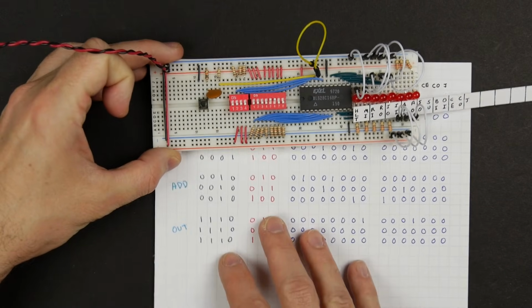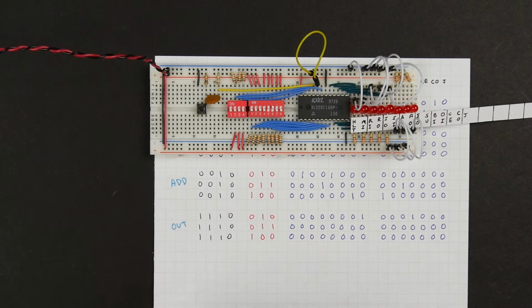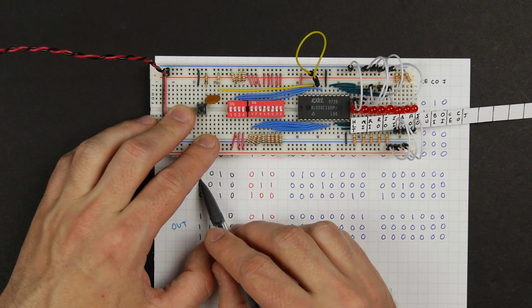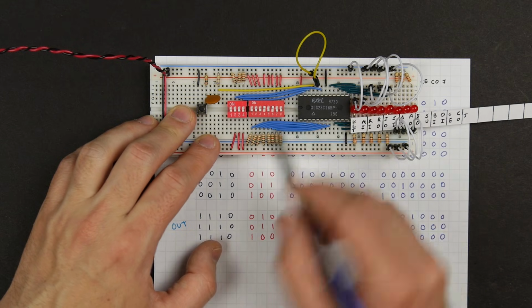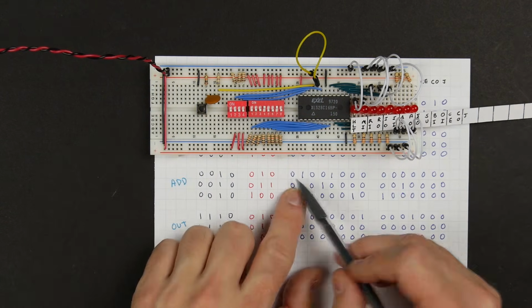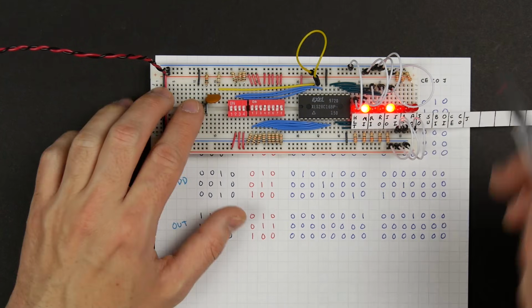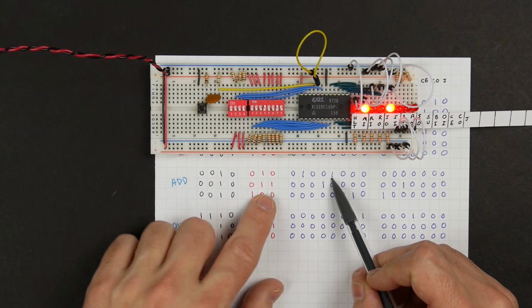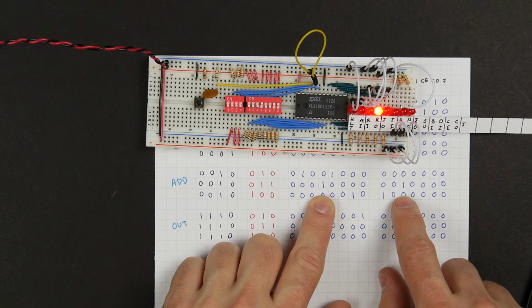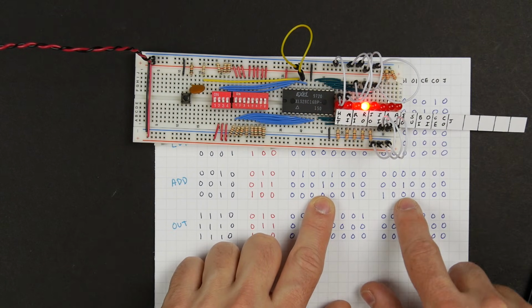So next we've got the add command. And so add command is 0010, the opcode for the add command. And then we'll go back to step 2. And so for step 2, instruction register out, memory address register in, that sounds right. Program that. Next step, that's RAM out. And then we're also going to do, it looks like, B in.